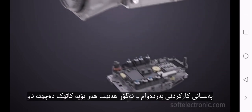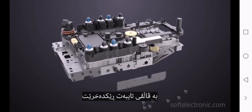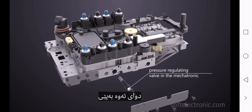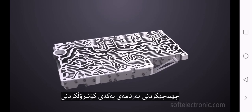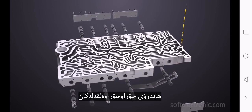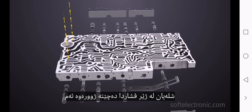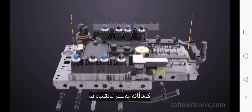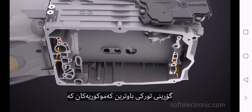That's why, when entering the valve body, the fluid pressure is first regulated by a specific valve. After that, depending on the program execution of the control unit, various hydro valves open or close the fluid paths in the plates of the valve body, letting in fluid under pressure. These canals are connected to the clutch packets in the gearbox and torque converter.